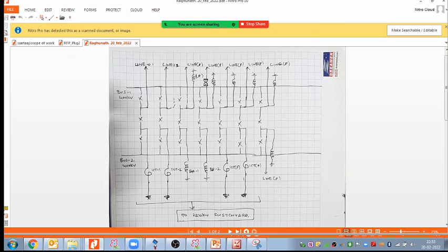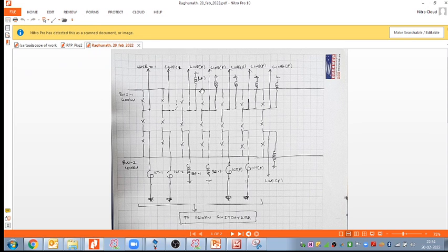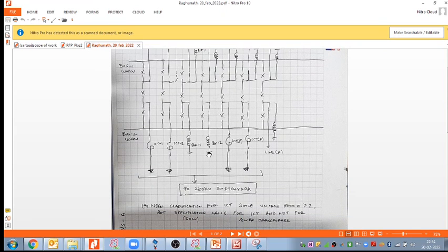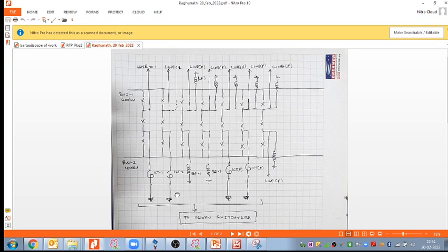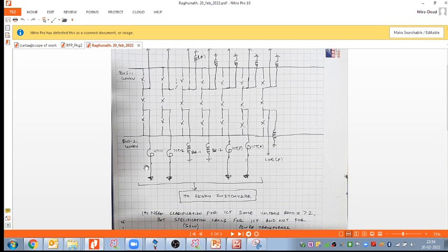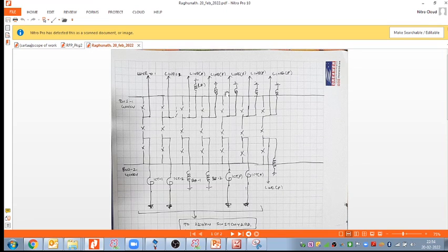That is mentioned in the tender, yes, it is mentioned that space should be considered for line reactors for future lines. Okay, then two line bays here. So this is my 1, 2 and 3, and this is my ICT 1, ICT 2, bus reactor 1, bus reactor 2. All right, and these are your future ICT bays. Okay, that is fine. Okay, line with the line reactor.